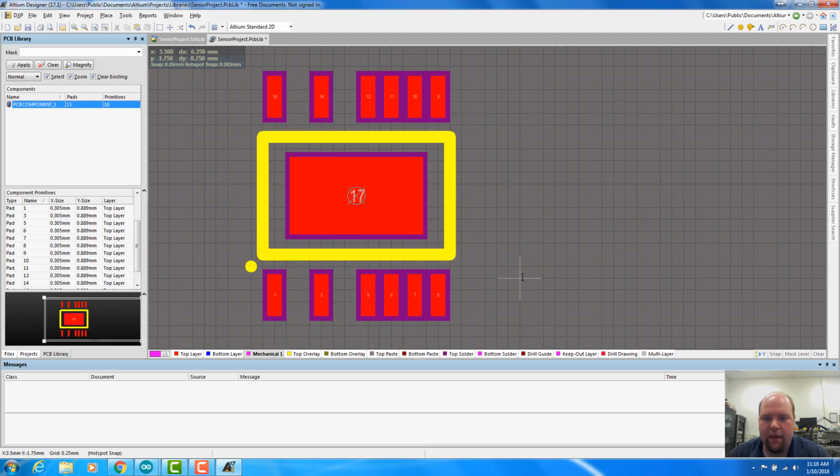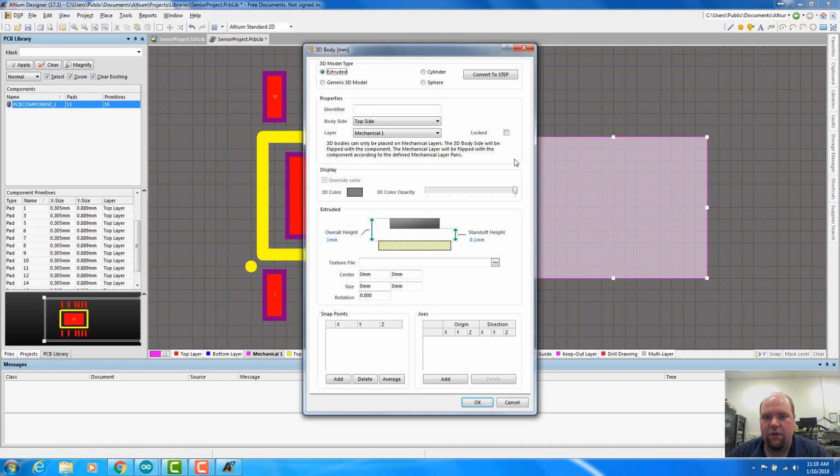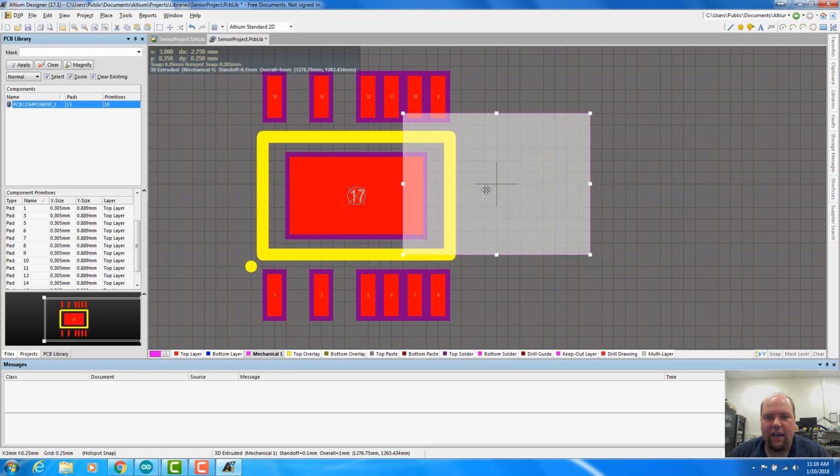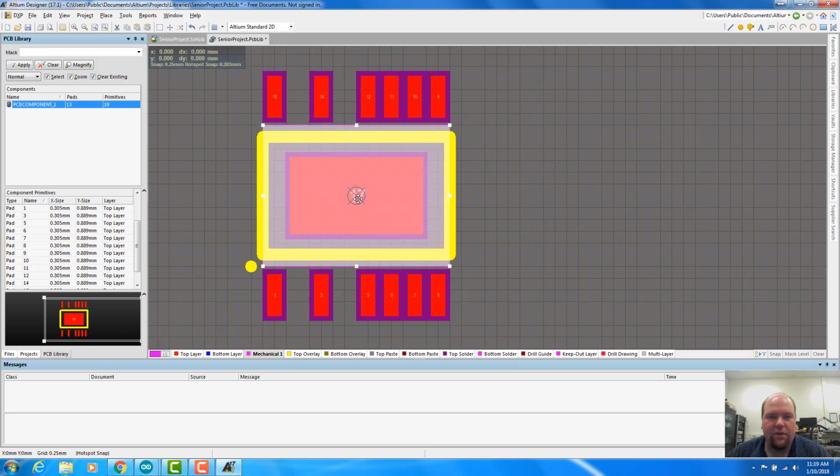the part. So I want it to be 4 millimeters wide, so I'm going to just move this until I see that dx go to 4 millimeters. I'm going to move it up until I see the dy go to 3 millimeters. Now I'm going to move it over until we get back to -4, and then I'm going to hit escape to close the polygon. And now we can move this guy into position.